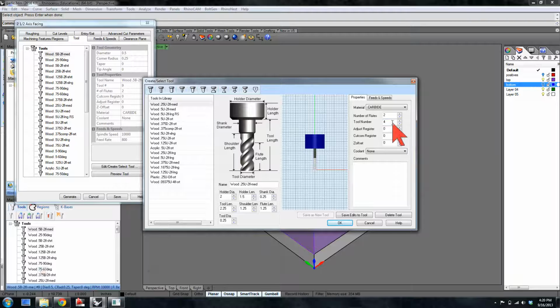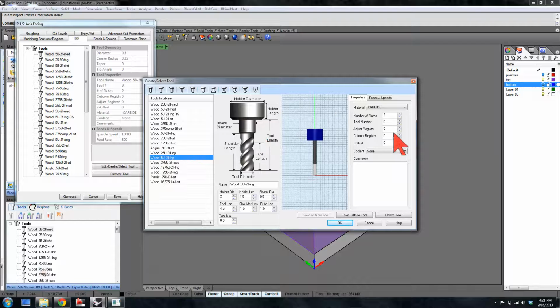Our tool changer has only 10 tools, so you want to make sure that that's one of the tools. And then you want to get to know which tools we have sort of permanently mounted in there, because if a tool is tool number 0 in the tool library, you'll have to change the tool before you can cut your file.